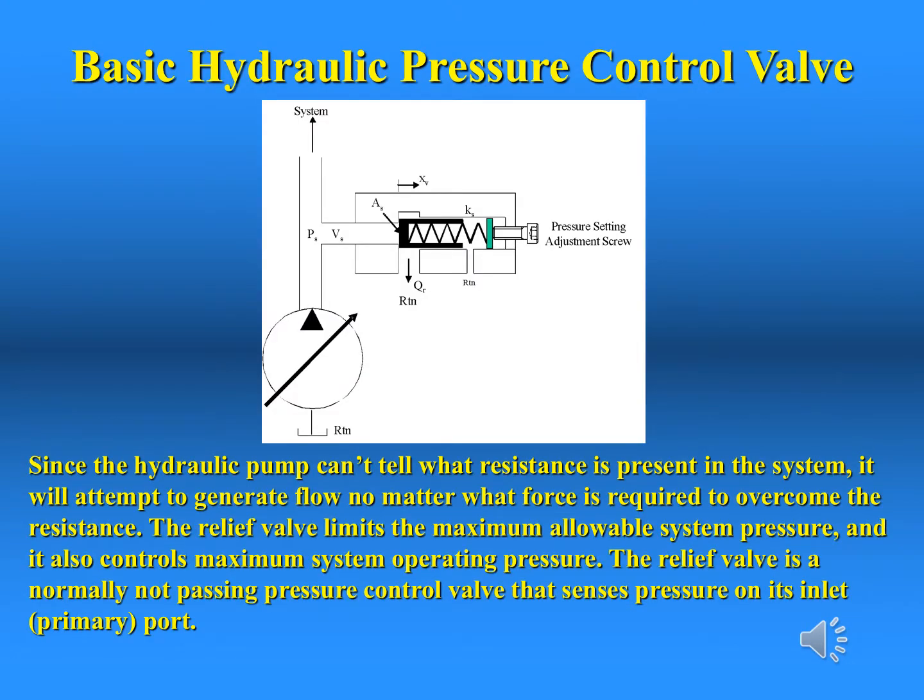This illustration shows how a simple pressure control valve with an internal movable member provides a path for oil to get back to tank when the pressure reaches a predetermined limit. The most common method involves the use of a spring to bias the movable member to the blocking position, and as pressure increases, allow the spring to be compressed as the movable member is pushed against the spring by the force of fluid. In this way, the relief valve acts similar to a voltage regulator, regulating pressure based on system demands. We will study two different design types in detail later in this course.